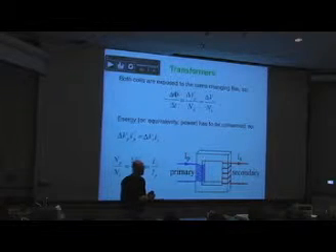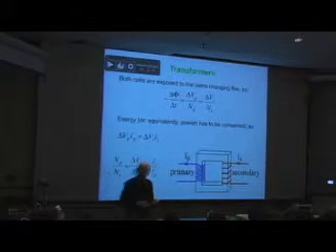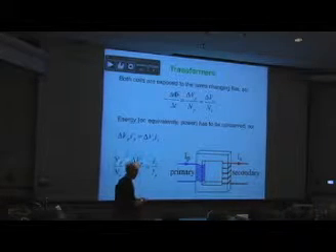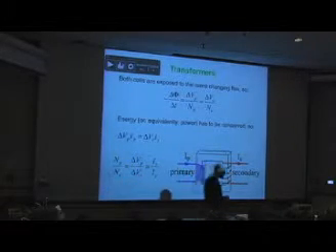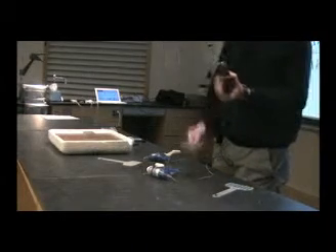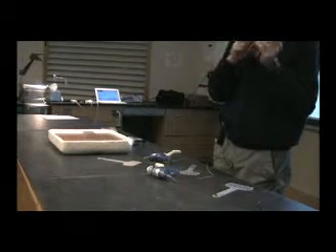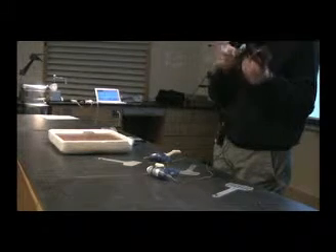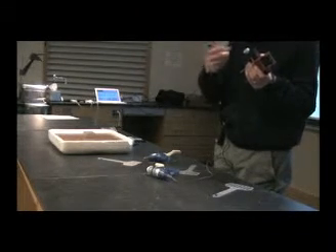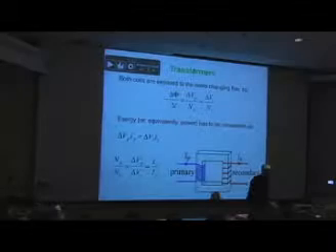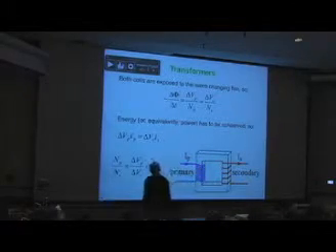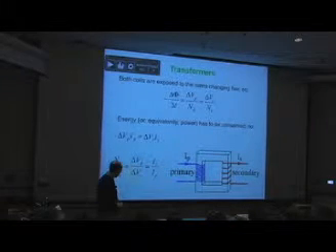Think about where we started today. What did we start talking about? Exactly right. It's all about eddy currents. Okay, so the laminations do what, like the slots do in this, right? The laminations prevent big swirling eddy currents that would reduce all the energy. You could dissipate all sorts of heat, thermal energy, in here if you allow those big eddy currents to swirl. So you get rid of those eddy currents by this. And for a power company, you know, power is money, right? So they do whatever they can to eliminate any losses.